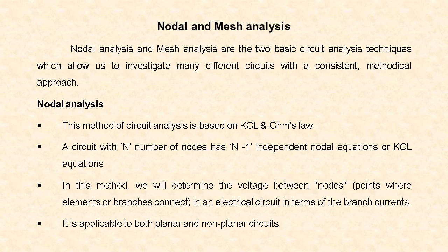Nodal analysis is one of the circuit analysis methods which is based on KCL and Ohm's law. KCL, that is Kirchhoff's current law, states that the algebraic sum of currents meeting at any junction or node is equal to 0. That is, the algebraic sum of currents entering the junction or node is equal to the algebraic sum of currents leaving the junction or node.